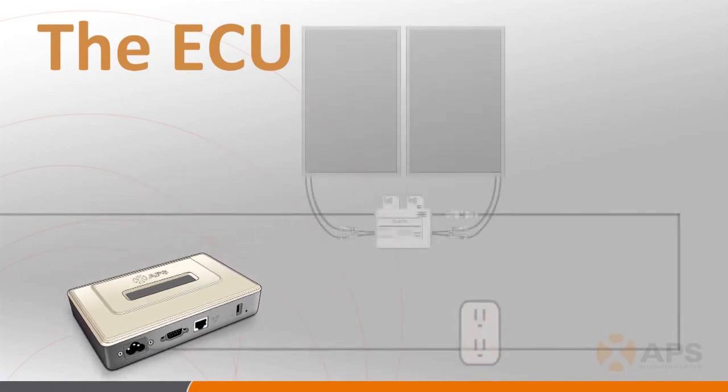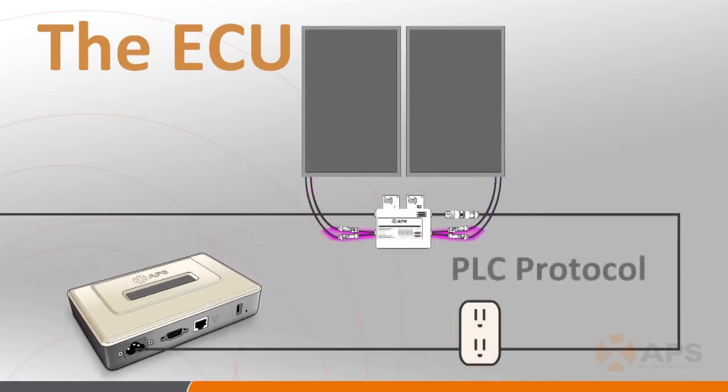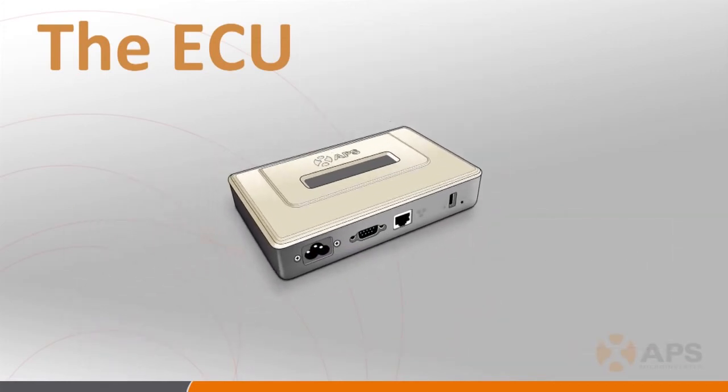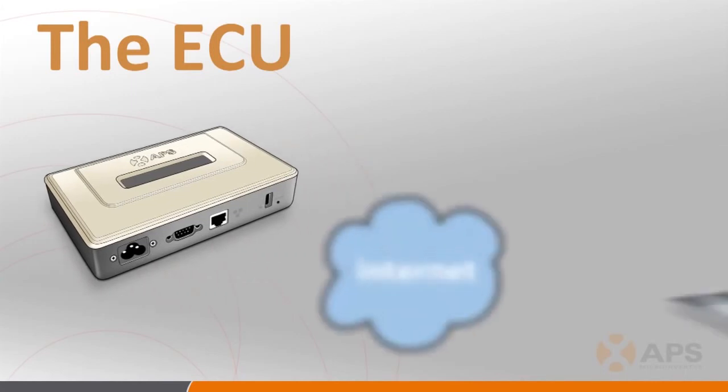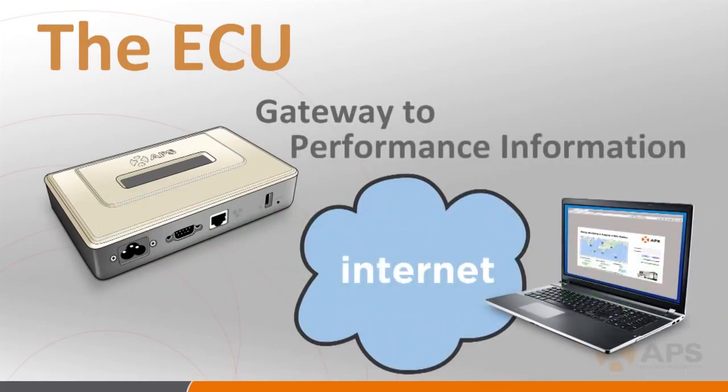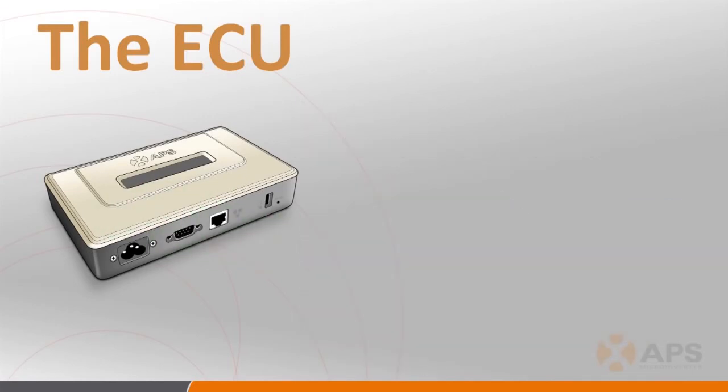As mentioned earlier, the ECU collects and stores the performance data from each of the microinverters using the power line communication or PLC protocol, and sends it to the APS database via an internet connection so that the array can be monitored online. The ECU, while optional, is an essential component of the remote monitoring system that should be thought of as the gateway to the performance information that can be retrieved from each inverter and its assigned PV modules.